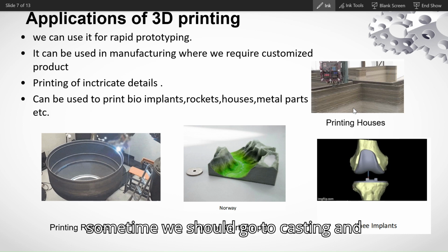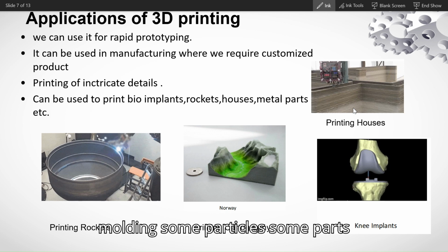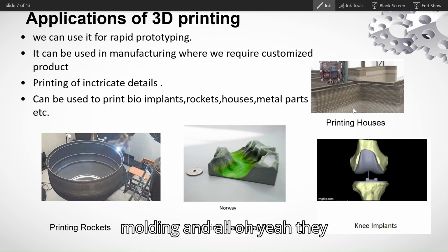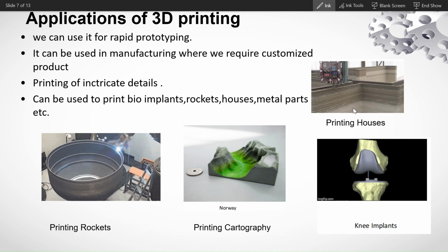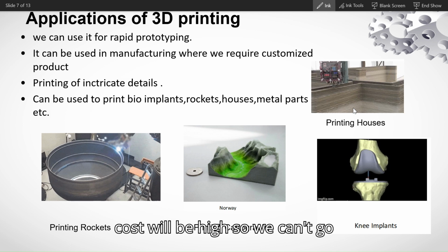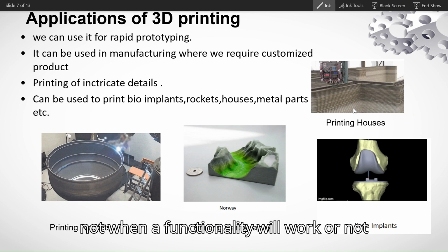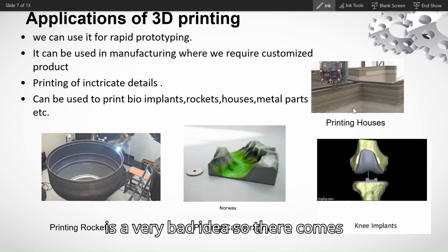There are also issues with injection molding, but sometimes they go for injection molding or silica molding. But as we know, mold cost is high, so we can't go for a mold every time. Suppose I want to try a new design and I don't know whether the functionality will work or not. So the mold concept is a very bad idea.